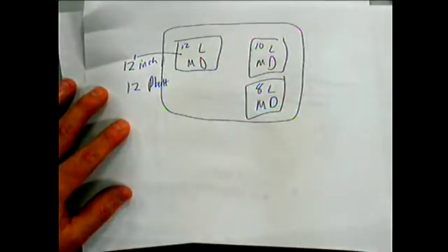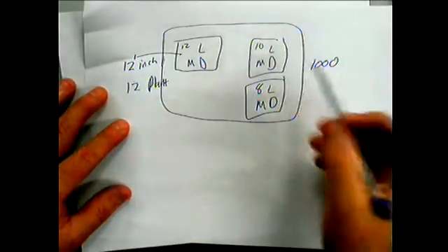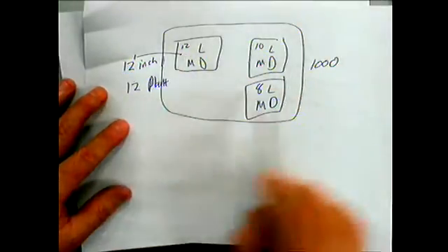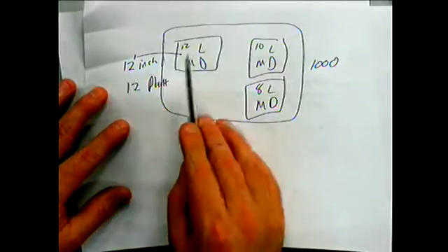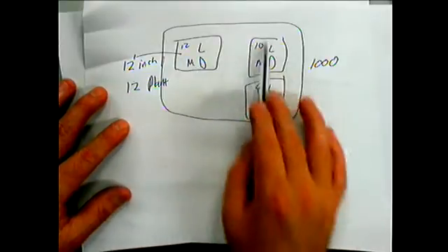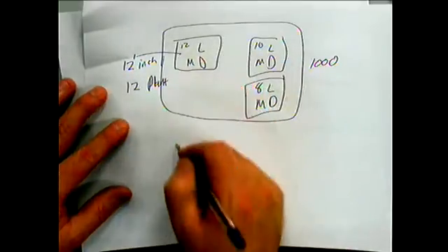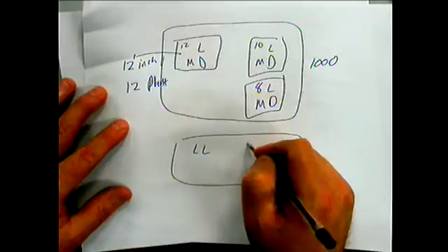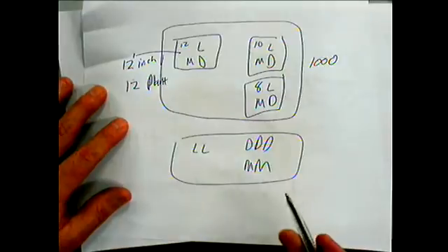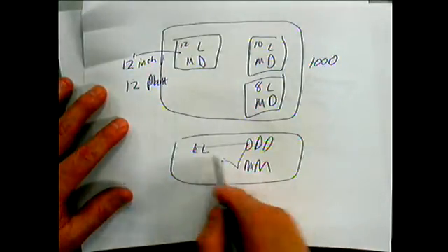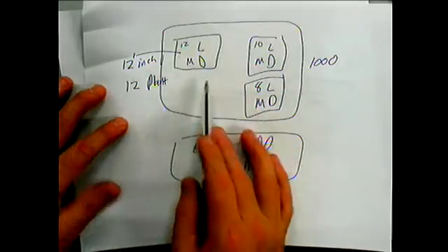See what I'm saying? Don't have a factory that does 1,000 products. Have a factory that has 4 little factories inside the big factory. Okay? So that everybody knows that they're responsible for 12-inch and doesn't get confused with the 10-inch workload. This is expensive because I might be able to do a similar factory, which was lathe, lathe, drill, drill, drill, mill, mill, cut out a lathe and a mill, still have enough capacity, and then just route the material like this. But then things can get lost. Whereas this is much simpler because these guys are always doing 12-inch.